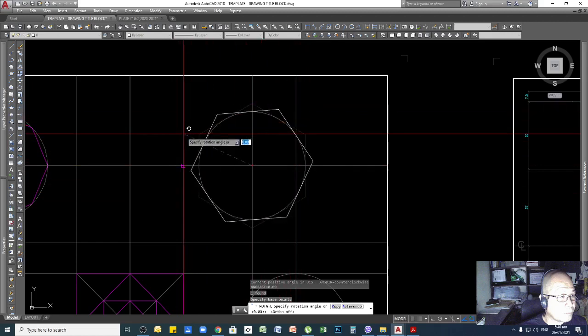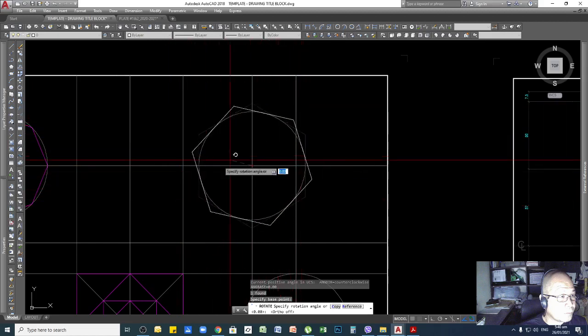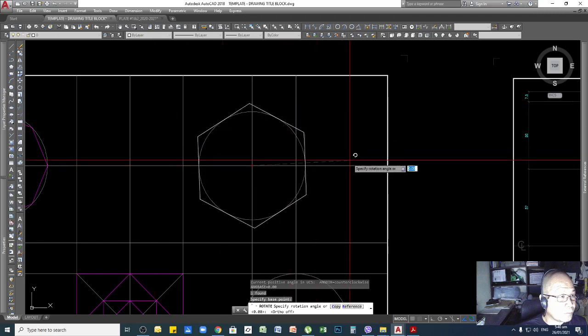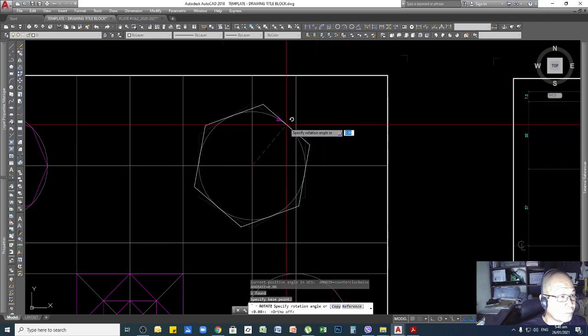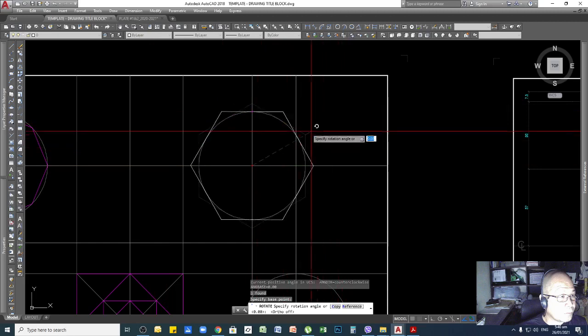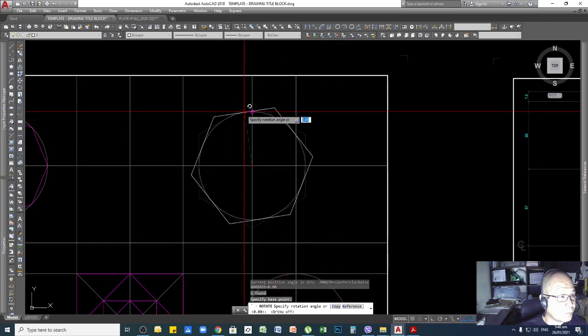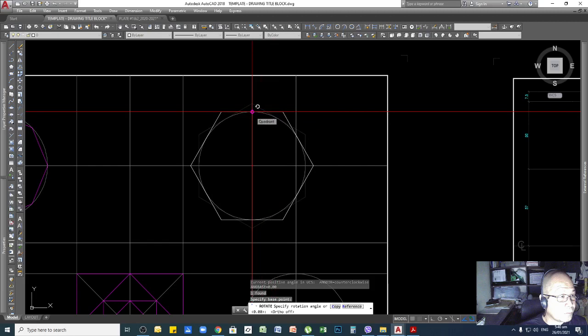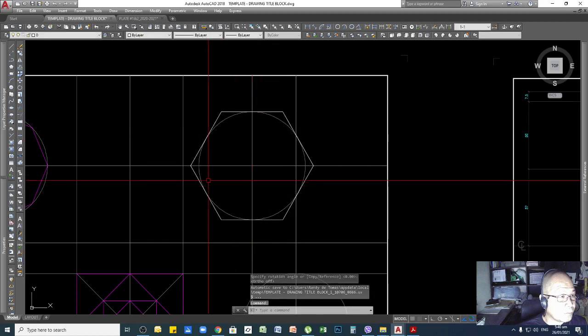So all I need to do is rotate it, either I go left or I go right, so that this portion here will go here, right? Or because the object snap is locked already, instead of entering the rotation angle which the computer is asking, you can either type 30 to go here, or you can just click if your object snap is set like that.